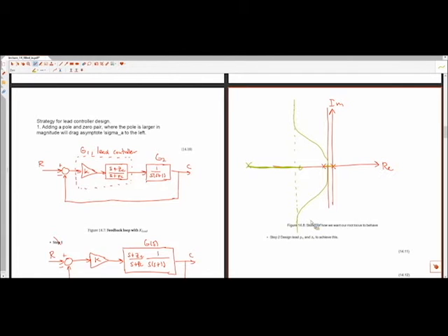Mathematically, you can definitely do that. That's perfectly legal. In practical aspects, that's going to cause a lot of oscillation in the system as you're no longer filtering that derivative, which can have negative effects on noise. That's kind of beyond the scope of this class, which is more theoretical, but practically that would not work very well. Yeah. Ben?